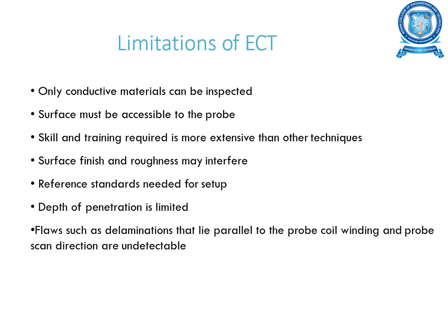Eddy current testing also has limitations. Only conductive materials can be inspected, and the material surface which you are going to test should be accessible to the probe. The skill and training of the tester is required, and it's more expensive than other techniques. Surface finish and roughness may interfere, and reference standards are needed for setup. Depth of penetration is also limited, and delaminations that lie parallel to the probe coil winding and the probe scan directions are undetectable.